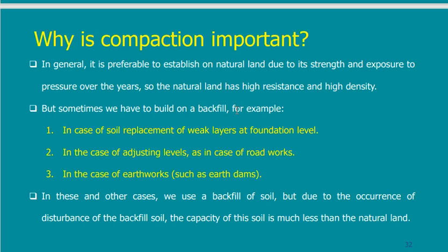Usually these layers are between 25 to 30 centimeters maximum. You cannot put more. This is a very important number that you have to memorize by heart. 25 to 30 maximum. This is the height of the layer.